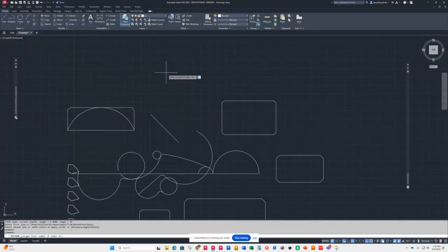So there you go. Anyway, pentagon has 5, so we type in 5. And then you have to pick a center point. Then it asks you the question that really messes with people: would you like it inscribed or circumscribed? What does that mean? Well, to give you a hint, they help you out. Inscribed means it's inside of something. It's inside a circle, to be honest.